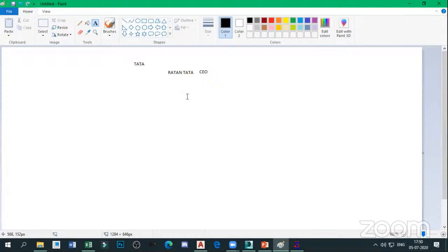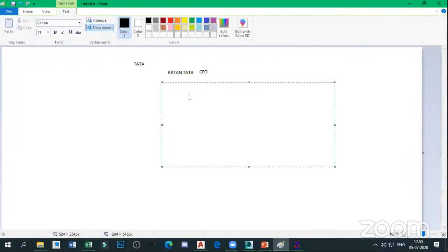Before I explain about Primavera, there are three categories in there: OBS, EPS, and WBS. Not about political parties. It's about organization breakdown structure, enterprise project structure, and work breakdown structure. This is the most important thing, so I will note it down here. OBS defines organization breakdown structure. Then EPS is about enterprise project structure. Then finally WBS and activities, that is called work breakdown structure.